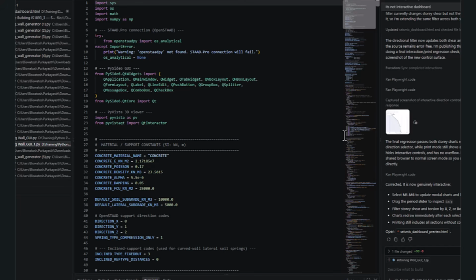Essentially, the soil behaves as a compression-only spring. This soil reaction acts normal to the curved surface, so its direction continuously changes. Since STAAD defines the compression-only spring in the global direction, a conventional spring definition cannot directly represent this behavior. Therefore, we need an alternative approach to define the spring action correctly along the curve profile.